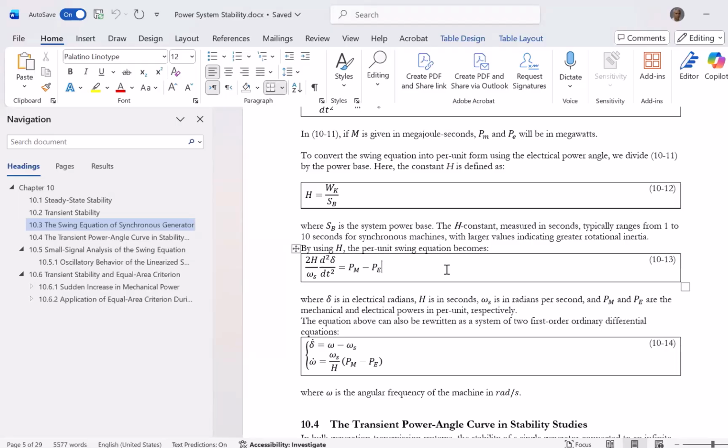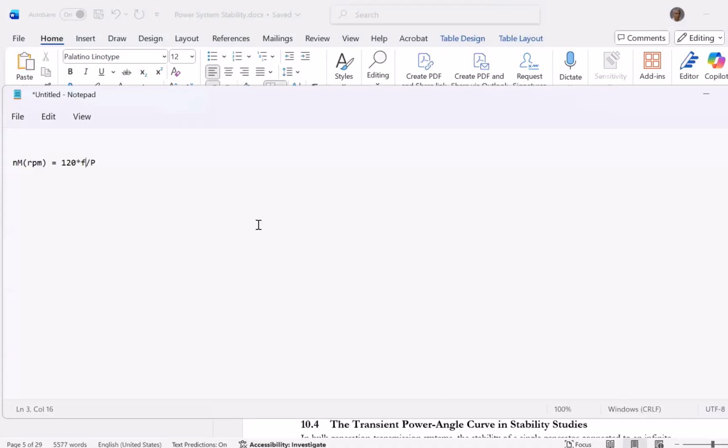Mechanical systems are slower in nature, but electric systems can be very fast. As soon as you turn the switch on, you're demanding more power. So where should that extra power come from? From the generator. The first place you can extract that power from is the mass of the generators, which translates into slowing down. Deceleration. That deceleration means underfrequency.